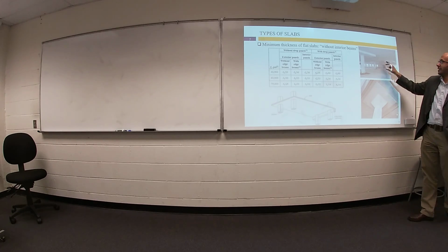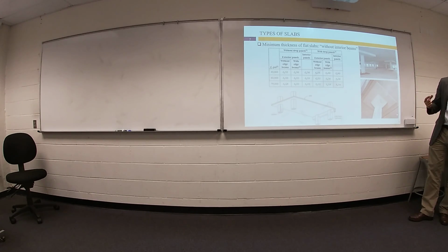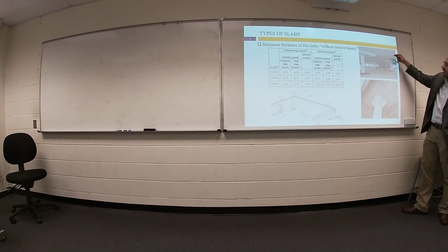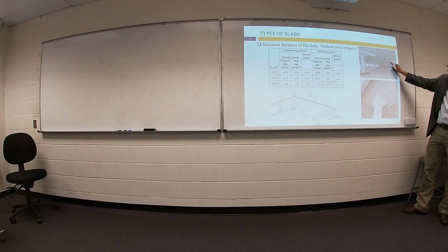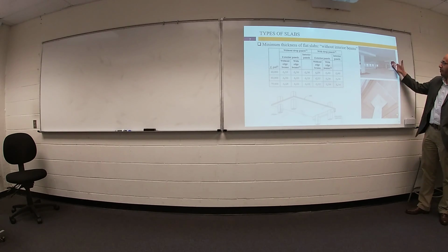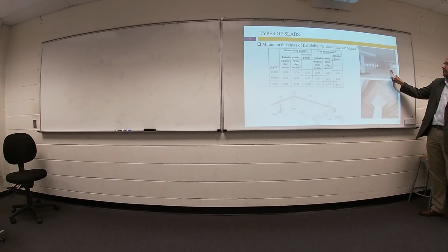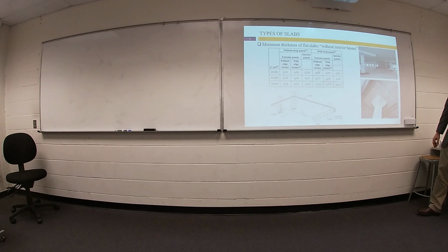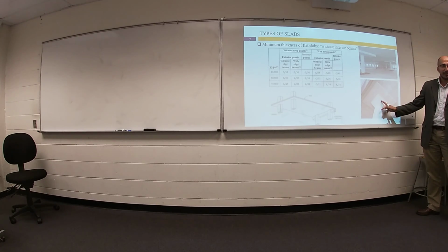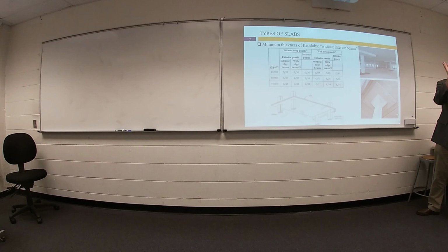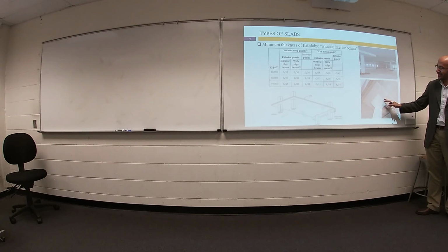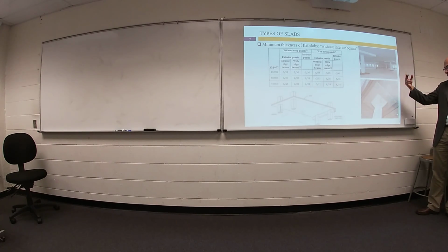Okay? So this shape is called drop panels. The thickness of the slab at this location is the original thickness of your slab plus the thickness of the drop panel. Sometimes, if your drop panel is not enough also, you have a huge amount of load and you have a concern about punching, we can do something called capitals. The head of your column. Your column has a head, and after the head of the column, we have the drop panel. Then we have your original slab.